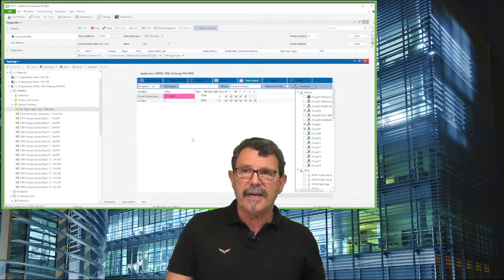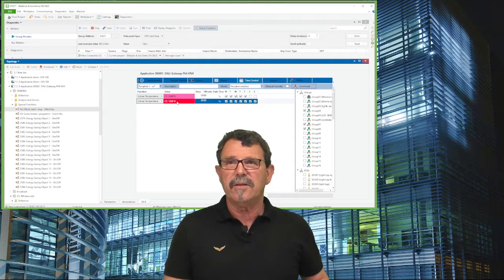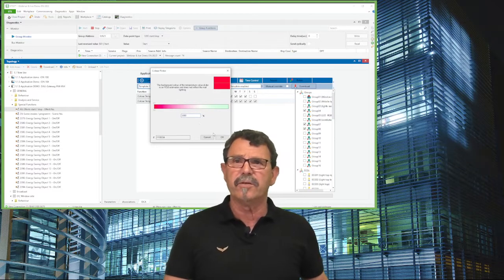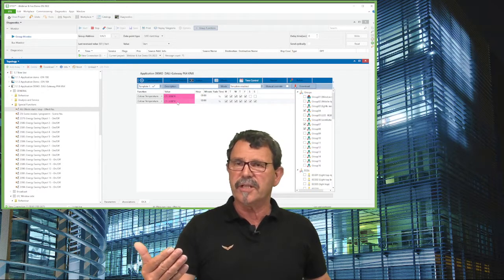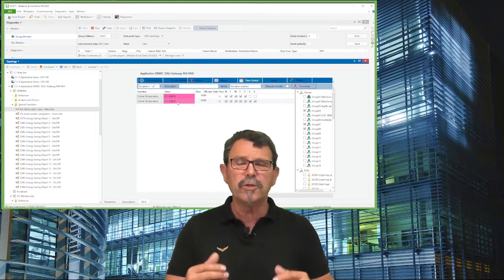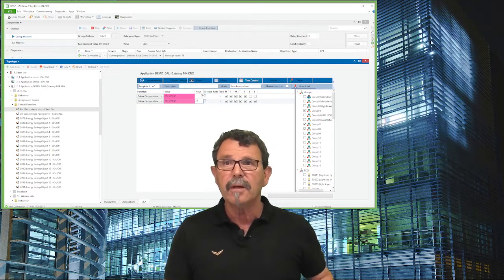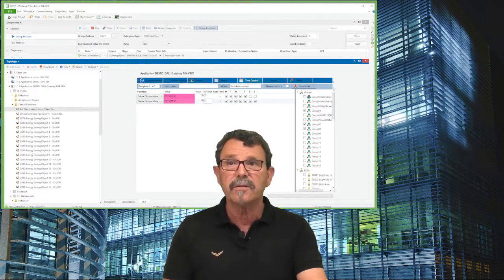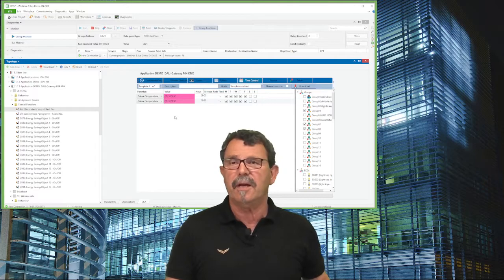So I import or I add another one, which is again color temperature control, yes. And then, for instance, open the color dialog, and now we do a step ahead. So that means a few minutes later or half an hour later, however, it's your choice. So we want to change from 3000 K to 3200 K. So it turns from a warmer light more to a colder light finally. Here you set finally the time again, 09, and then we do have here, for instance, let's assume it's 30 and no fading time, so I leave it like it is, and you know how it works finally.